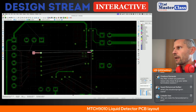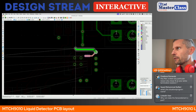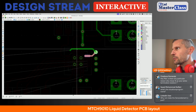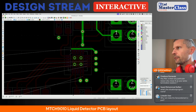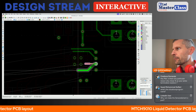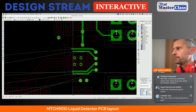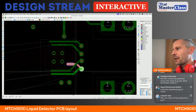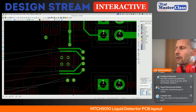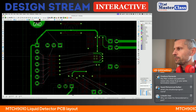So there is not excessive space, so I will carefully route them here and here, and as we said, we need the polygon on the bottom side connecting the reference plane, which is ground, and ground is on the exposed pad, and we need the entry point here.